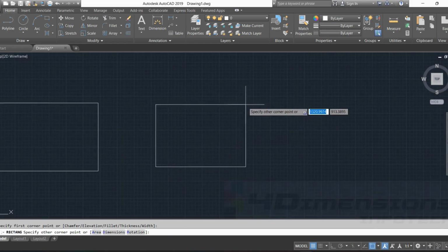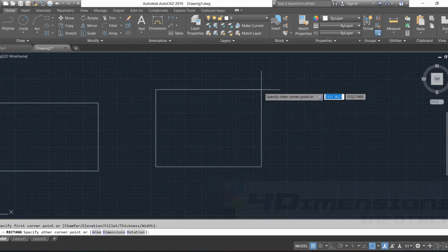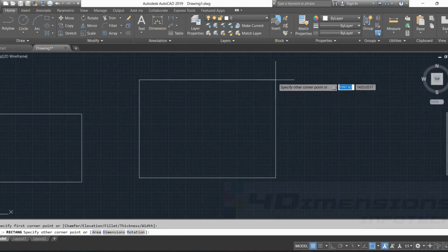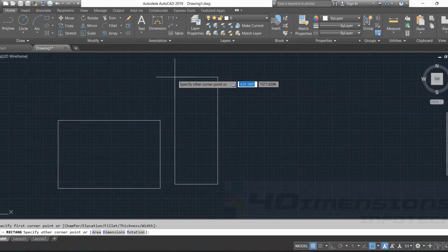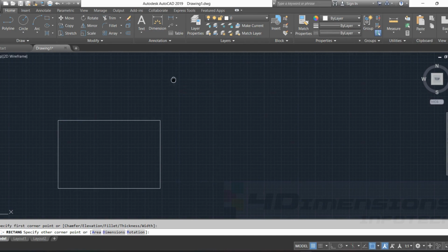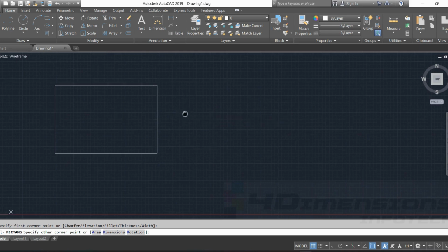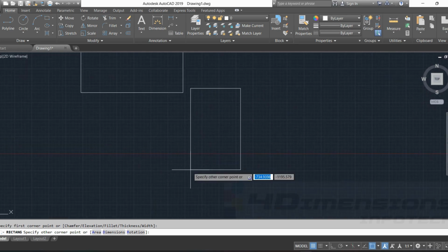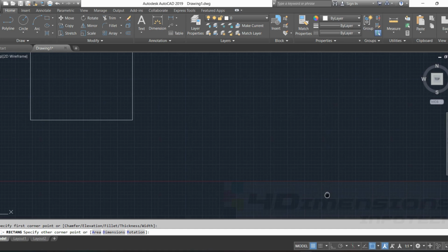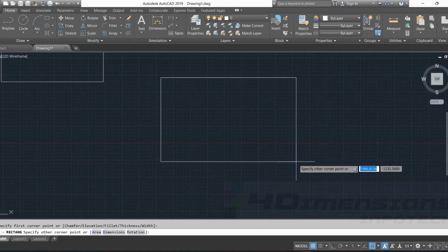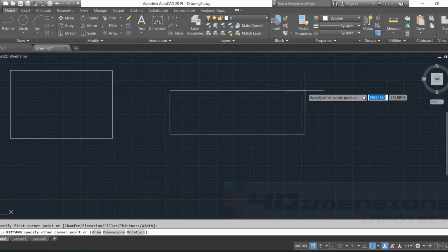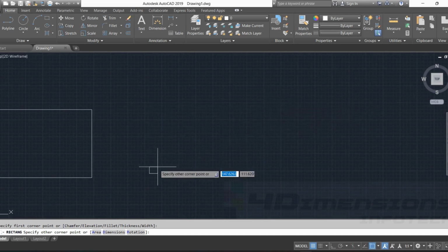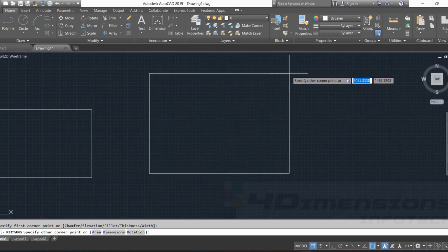As I said, we need to drag the rectangle from lower left side to upper right side. This is the first quadrant in which we are dragging the rectangle. Suppose if I go in second quadrant, you can see one value is coming negative and the other one is coming positive. If I go in third quadrant, again both the values will come in minus. If I go in fourth quadrant, X is coming positive and Y is coming negative. That is minus value. So that's why we have said it is better to drag the rectangle in first quadrant only, from lower left side to upper right side.